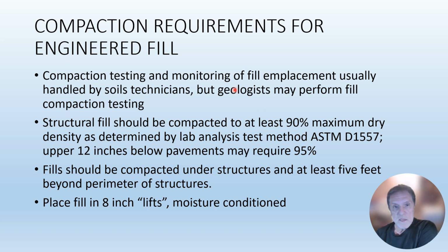The compaction testing of fill during grading operations is usually handled by soil technicians, but geologists can also do that and can keep an eye on practices of filling. You've got to compact under the structures and 5 feet around the perimeter of the structures at least. Place the fill in thin lifts, and moisture condition each lift or layer as you go.